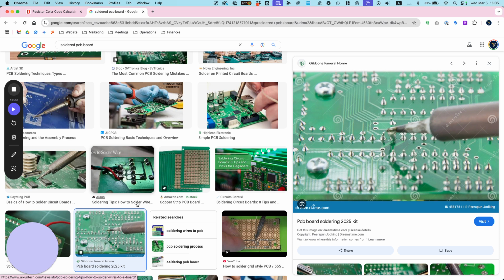Hopefully that makes a little more sense, right? So you can hot swap it. More than likely your drone is doing the same thing, it's just increasing capacity. So you can hot swap for the same reason. I actually didn't know you could do that with the Inspire either. So the Inspire, yes, you can. You don't actually have to turn it off. You can take out one battery, put in a fresh battery, then take out the other one, put in a fresh battery. Just in case that extra minute is life-threatening or something like that, you need to do something.